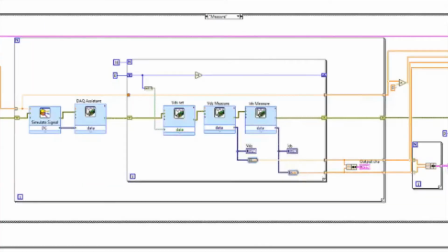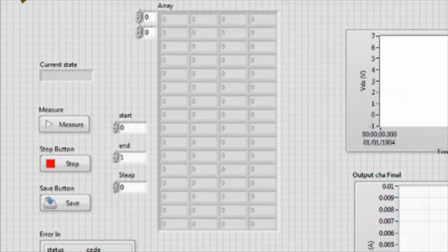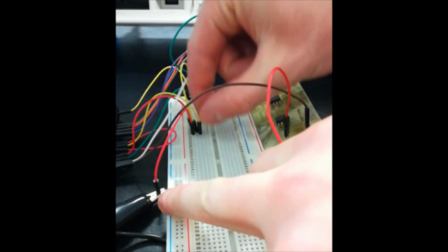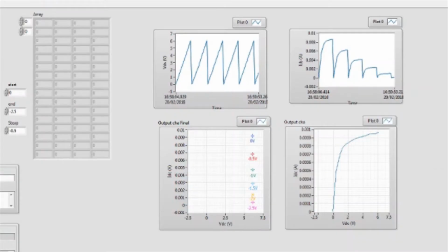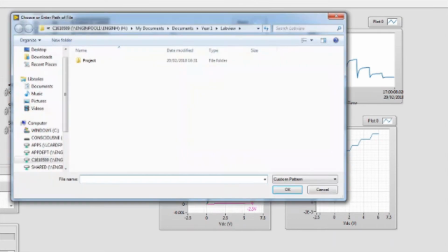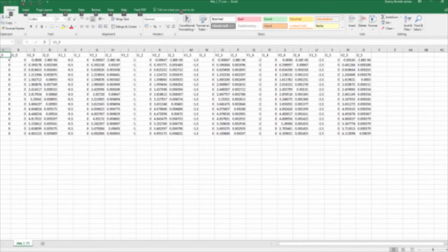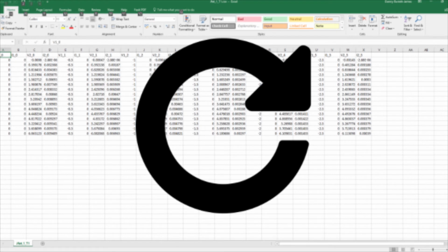This for loop uses an increment block to count from 0 to 15. These numbers are then put into the data input on our DAC systems, where they are fed through into the summing amplifier and out onto our transistor. VDS and IDS are displayed on graphs and then stored in arrays for later use. This process repeats until all the tests are completed.